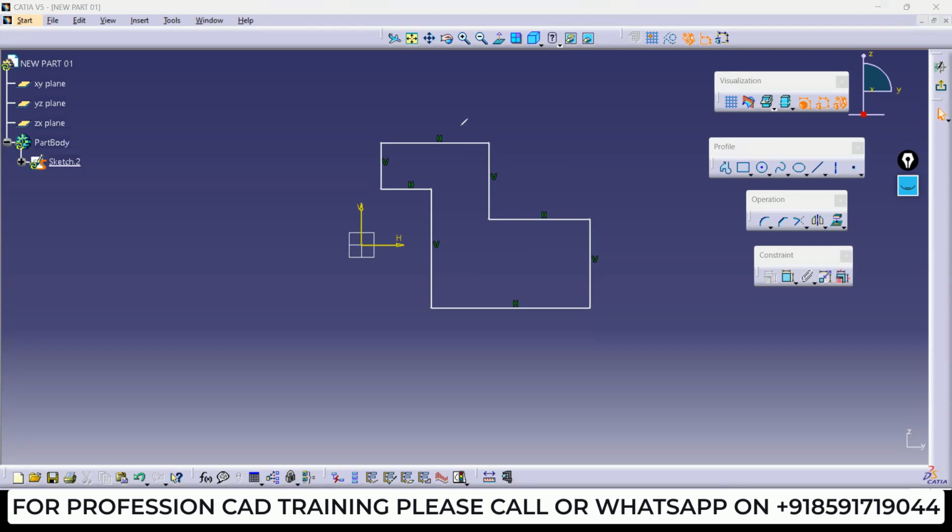There are two types of constraint. One is a dimensional constraint and second is a geometric constraint. If you go here, you can see dimension constraint and automatic dimension constraint also will be there. Geometric constraint and dimension constraint, the color is orange, means both the options you need to keep on. If it is off, just keep it on.